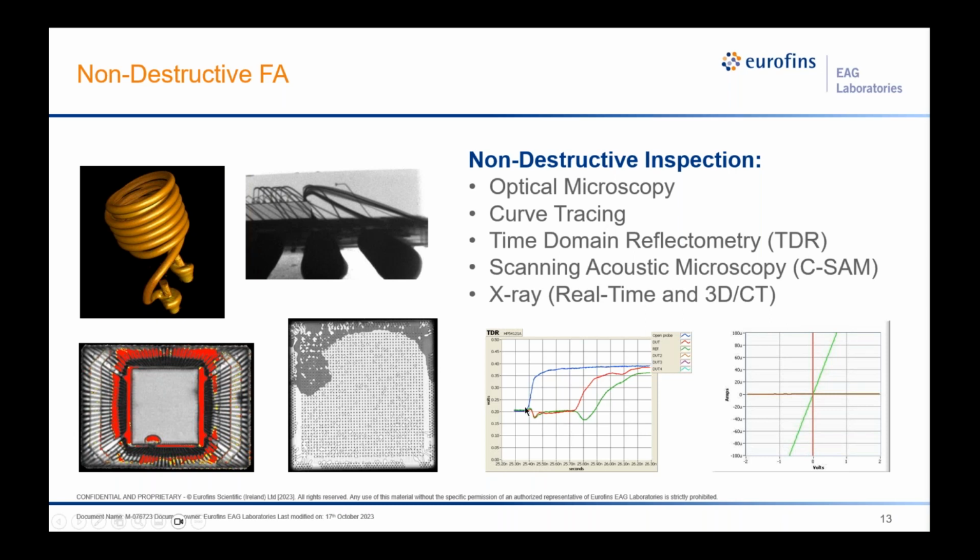And so if we take the time that it takes to come back to the origin, we can detect, based on the trace path and the materials involved, and estimate how far the break was from our origin. That gives us an idea of where potential breaks or cracks or opens can be within a package before actually having to do anything destructive, and therefore paves our road to how we want to go about either doing a cross section or P-lapping or whatever the physical analysis steps would be.